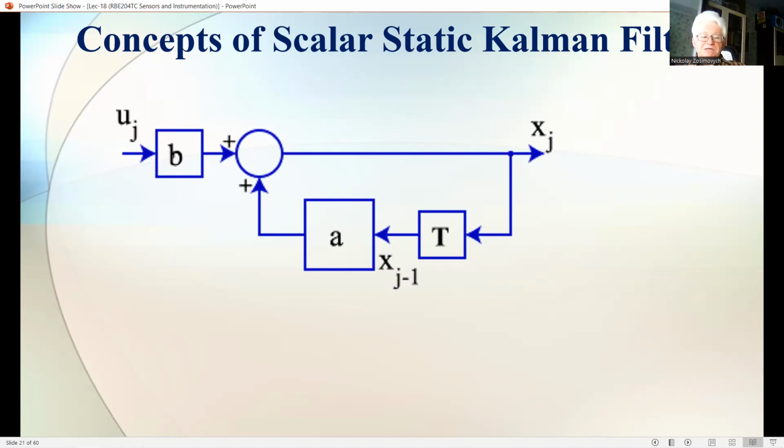In deriving the present recursive algorithm, we make the following assumptions. First, when there is no measurement error, the measured or estimated parameter M and the measurement data Y are linearly related through a known constant gain C, which is called the measurement gain.